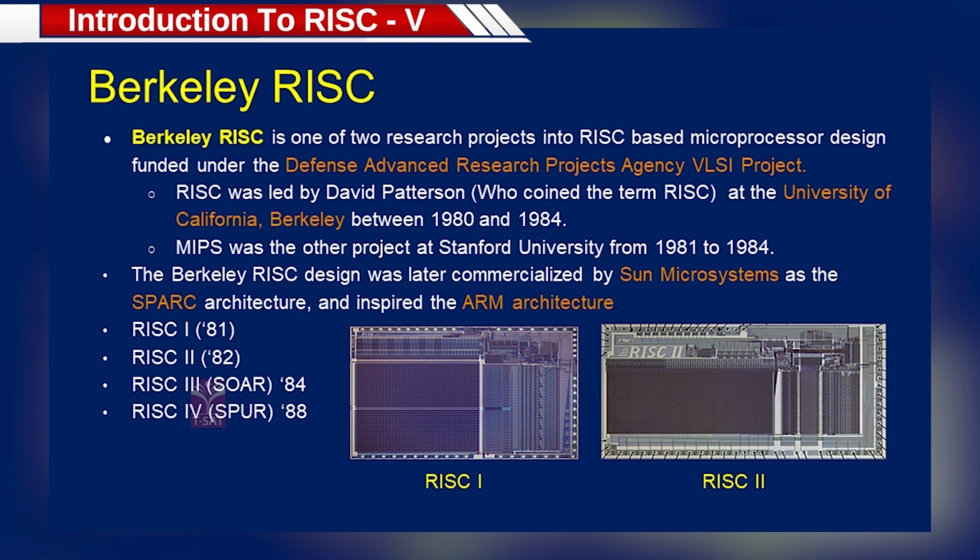But the whole point of the RISC effort is that I'll have a lot fewer instructions, but a lot more registers, so that I get the data and have it on the chip, and then execute it, and they don't have to go to memory to fetch those instructions. They're all local, so they'll run faster, and the overall execution time for the entire program is a lot faster. So that was the idea anyway.